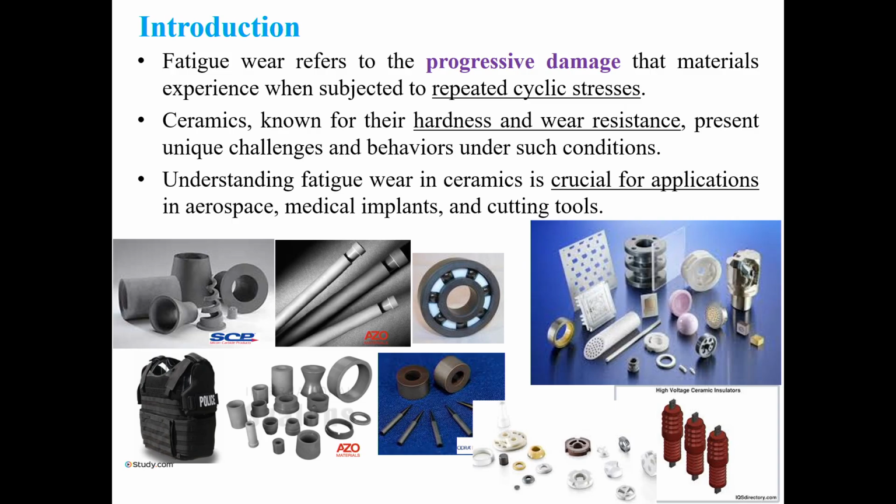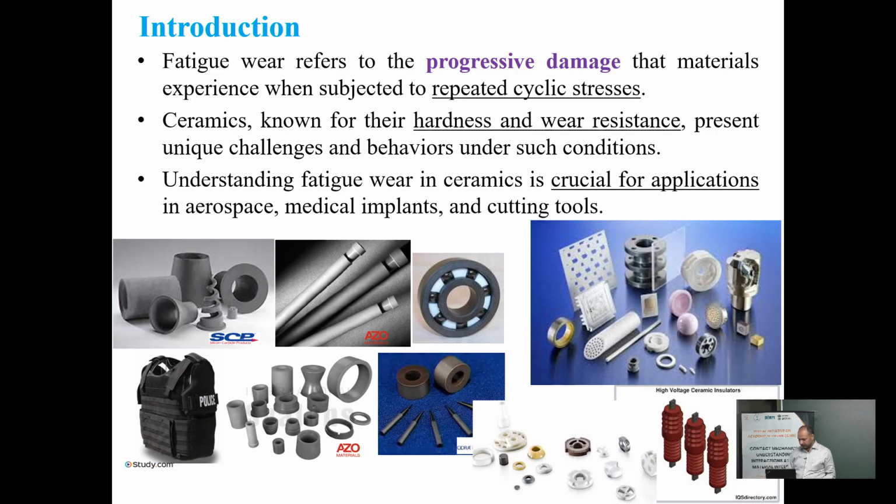That leads to their application; they are very promising elements to use for wear applications. These are the engineering applications you see: nozzles, heat exchanger tubes, bearings, and then ballistic materials. Those are all applications where ceramics are used very frequently, considering their very high hardness. At the same time, they are corrosion resistant and wear resistant as well.